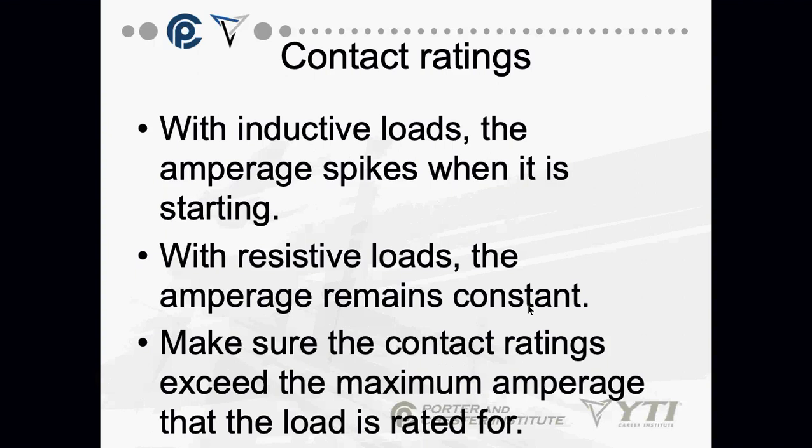Now, here's the important part. With inductive loads, the amperage spikes when it's starting. Let me see if I can explain that a little bit. When I first turn on a motor or energize a coil, for a split second in there, there's no resistance. If there's no resistance, the amperage goes way up.